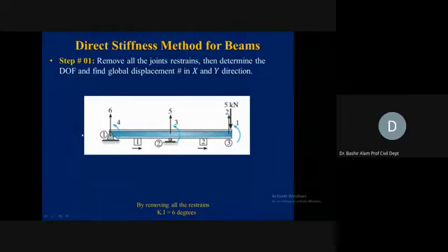It depends on how the stiffness coefficient matrix which we developed was produced. Translation followed by the rotation. Now remember that order is important. The first column was coming from the translation and then followed by the rotation. So our address now will become 6 4, not 4 6. It will be 6 4 5 3.